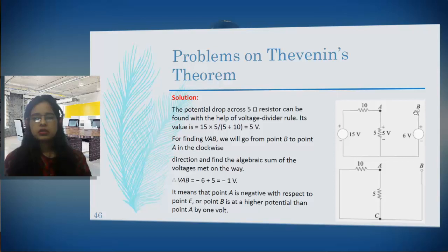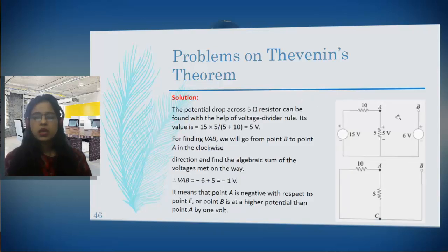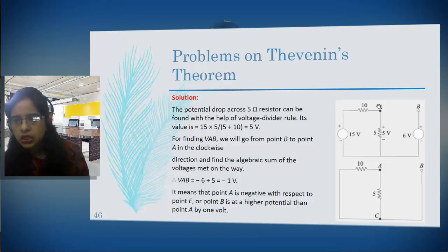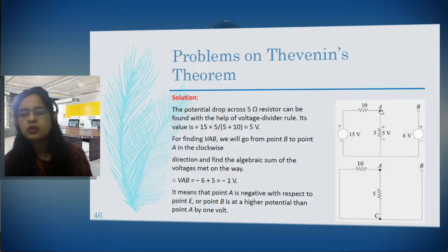So this is open, right? When we remove this, it will be open. Now we are supposed to find out the voltage drop appearing across this A and B. Now see, between B and A, when I consider like this, there is a voltage source present. So whatever voltage drop appears across AB will not be equal to the voltage drop appearing across this.